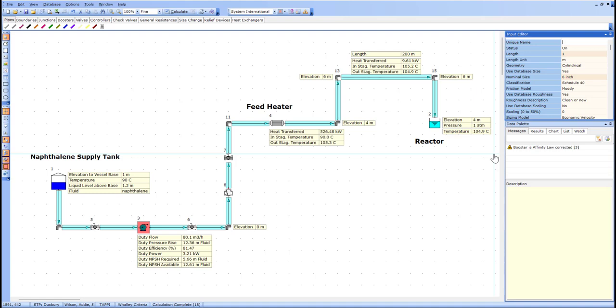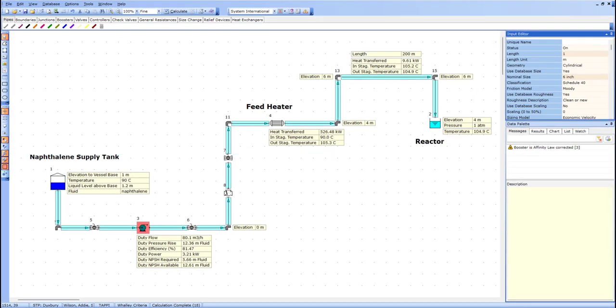With only about a 25 degrees Celsius margin above the solidification point, losing 7 degrees Celsius in bare pipework is significant. And steady-state operation isn't the only consideration. Startup before the line is warm, shutdown with fluid remaining in the pipe, draining, heat tracing, and low points where solids can collect all affect whether the system operates reliably. For molten service, these aren't secondary considerations, they're fundamental to the design.